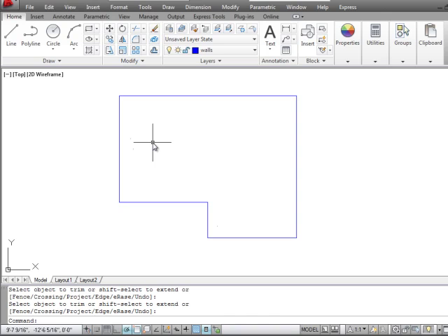We started a new drawing with English units. We then went to format units and set it to architectural. We then drew one line in that was much longer than the width of our current screen, say the width that we're going to want our building, and then zoomed out and we could continue on from there.